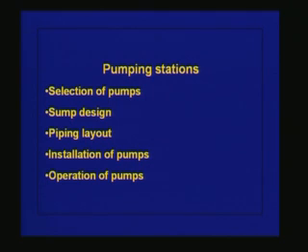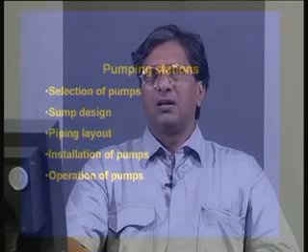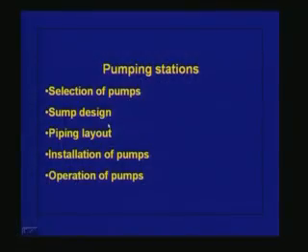The sump design itself is very important, and in fact many of the pump manufacturers insist that a model study should be conducted while designing the sump, and only if the sump design is satisfactory, then the pump manufacturer will give you the guarantees regarding the performance of the pumps, because the performance of the pump, as far as the efficiency is concerned, the life of the pump is concerned, is integrally dependent on the design of the sump. So these two are what we look at in this particular lecture.